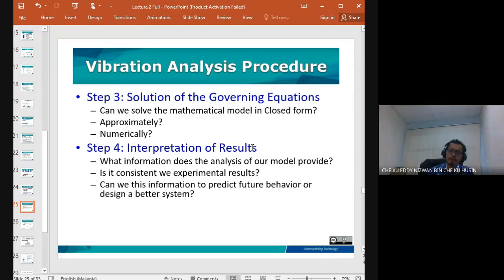Okay, once you run the software simulation and you have the equivalence with the actual measurements, then you can consider that your model is good and equivalent or identical to the actual system. So from that, normally for the modification of structure, they just do it in the CAD model, to reduce the time and to get a more accurate result. So you do the modification on the CAD model. For example, you want to stiffen the structure to change its natural frequency, then you can add another beam, for example, to stiffen the structure, and then you can see what happened after that. What is the value of the natural frequency when you put that kind of additional components. So that's normally used for the FEA software.